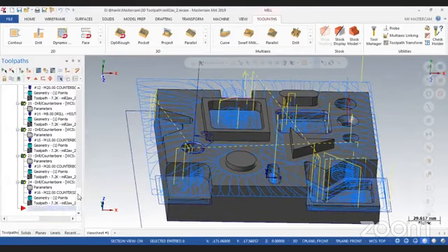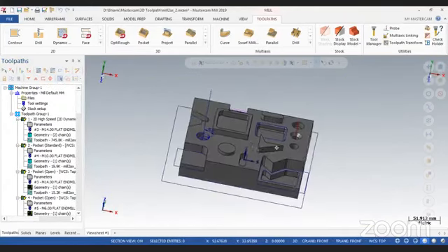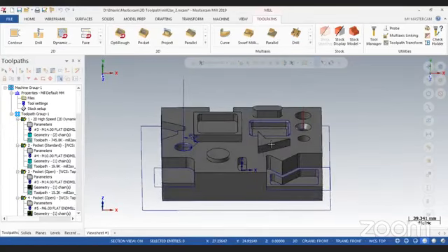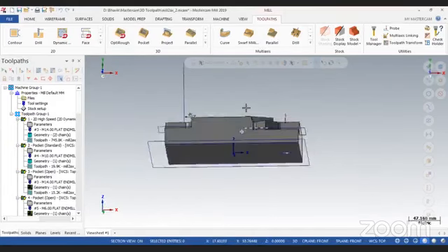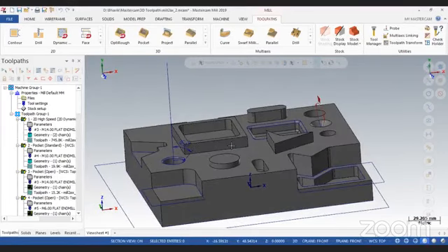So here are the details of multiple toolpaths. Let's say this is our CAD model. This is the final product we want to manufacture with Mastercam. So you just need to develop that CAD model and specify your blank part. I can explain the blank part in another manner. Let's say if you are manufacturing gears, then you need to have a gear blank, which will be like a disc only.